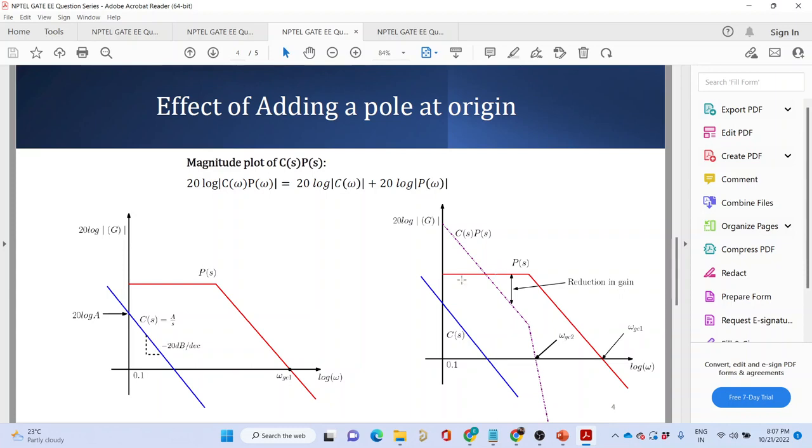So now what you have done is, by adding this integrator, you have reduced the gain over here. You have reduced the gain of these frequencies, the ones that you see with the double-ended arrow. These frequencies were responsible for making the system fast. If the gain is high for a certain frequency range, for the mid frequency range, then the system would track those signals also properly.